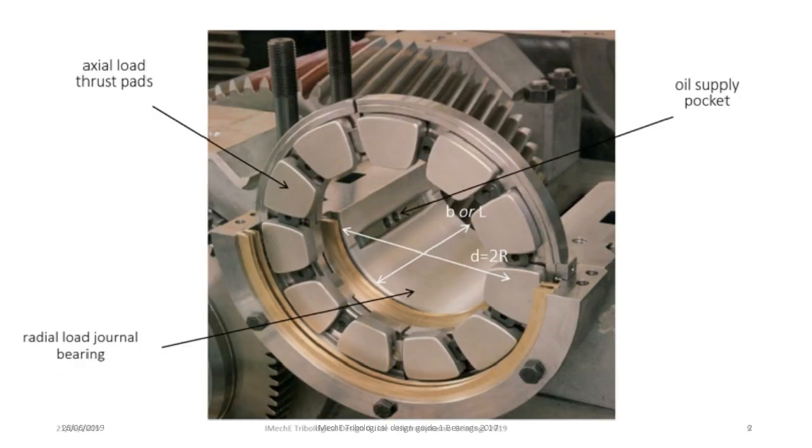This slide illustrates two sorts of hydrodynamic bearings. The journal bearing, which we can see in the lower half, is of dimensions B by D, and in this case carries a steady downward load. You can see the oil supply groove that is situated away from the arc of the bearing in which the fluid will be under a hydrodynamic pressure.